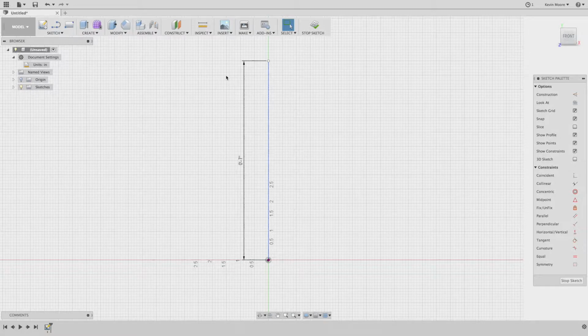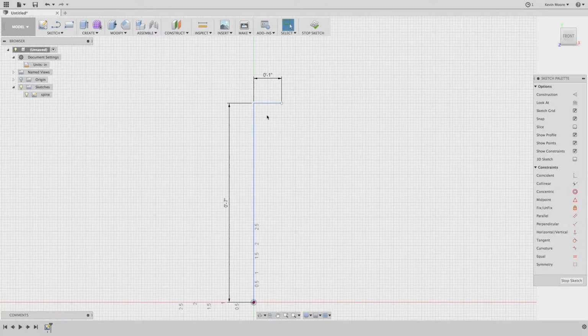And then you've got to think about how many sections you want to have in the bottle. Now if I click on this drop down window, I've got my sketch 1 here, and if I hover over it, it highlights, and I can title it spine or whatever, so that I can keep track of what the names are. You can turn the tools off and on there as well, and then I'm going to create another line from here in this direction. It doesn't really matter the length because I'm just going to set where I want my sections to sit in space.